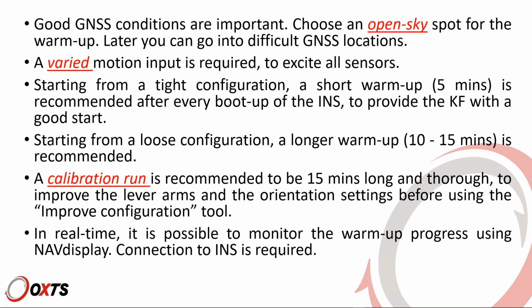A warm-up has to be completed in open sky, and we recommend a varied motion. In a minute, I'll detail what that means. Again, if you start from a tight configuration, 5 minutes is enough. If you start from a loose configuration, a bit longer. What we call a calibration run is this: at the beginning of this webinar, I mentioned that you do your best to measure the lever arms and orientation, and then you leave the system to figure out what the real measurements are. So your configuration is not spot on yet, and you want to get that.